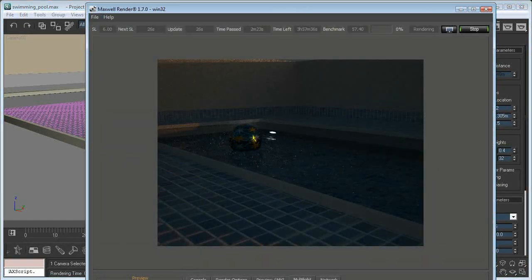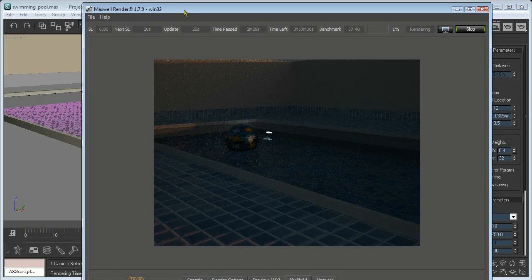The way to do that is it's all built into the shaders, and it depends on your reflectance and your refraction values, and also your render settings. If you're using mental ray, make sure you enable final gather, things like that, and have everything enabled that you need in order to do that.